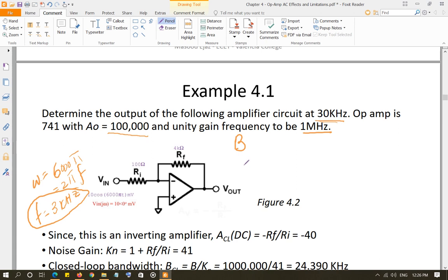So anytime you are analyzing, as you learn in AC circuits and circuit analysis, a circuit with sinusoidal sources, and you are looking for the steady state response, then you go from the time domain expression to the phasor or polar expression, the phasor domain expression. So you take the magnitude of the cosine function, and then you take the phase of that cosine function, and that becomes a complex number, the polar form of a complex number, and we hide the frequency and we hide the time and all those things. Right now the phase over here is 0, remember.